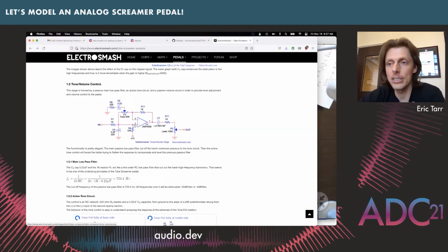What we want to be able to do is still assume that we have an ideal op-amp, and so there's no current flowing between the negative and positive terminals of the op-amp. So in order to still use this potentiometer as our main tone control, what we're going to do is split this up and assume that there are actually two different paths, one that belongs to this part from our input going down to ground, and then another path going from our negative terminal over here up to our ground, and there's no actual connection between these two things.